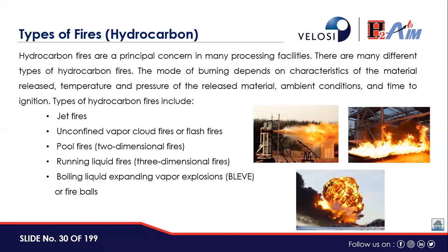These fires are normally in tanks, and then there is also boil over. For example, if a tank is under fire, sometimes there is a liquid or water inside below the hydrocarbon, and when the water boils, the boiling point of water being lower than oil, that boiling water pushes the oil in the tank, spreading it, and that is called a boil over scenario. And if the whole liquid is moving through, that's called BLEVE.